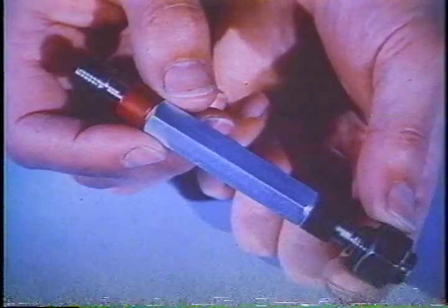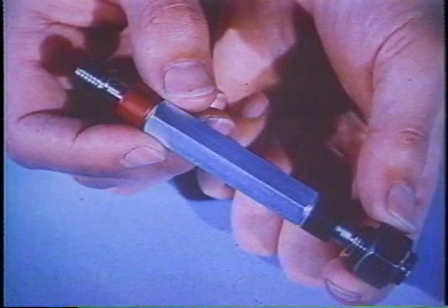A general method for measuring whether a tapped hole is loose or tight is by means of a thread limit plug gauge. The limits of the fit are machined into the ends of the gauge. The go thread being tested here should fit the hole, but the no-go thread at the other end will be too big.